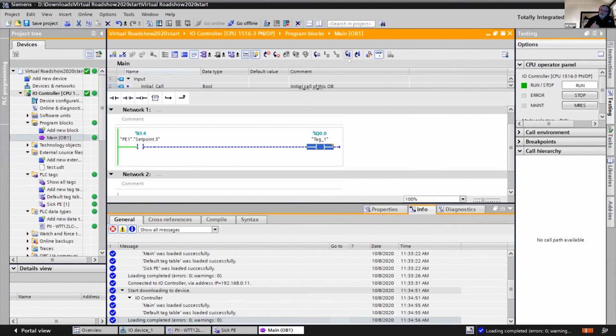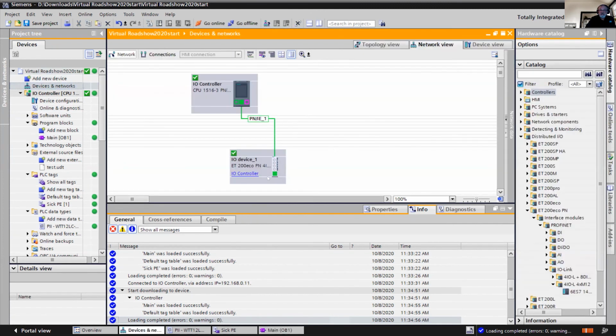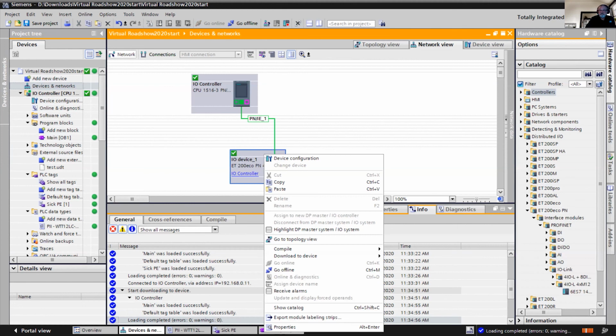IO-Link eliminates a lot of that. So now we can just have the 3 wire, and this is on an M12 connector. So we don't really do any wiring at all other than just connect it right up. We have an IP67 rating. We run them out along our conveyor system or large machine, and we can have lots of these guys. We may have several of them.